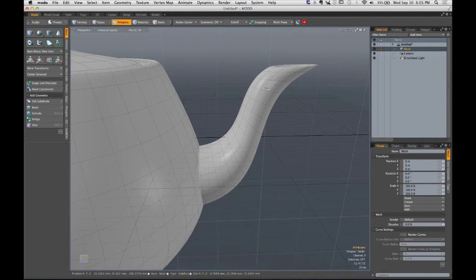now I can go in and you can probably begin to see the highlight color as I roll over all these polygons. What enables me to select the polygon? Clicking it with which mouse button? Left click. Okay, we're a left click centric selection system. If I double click on it, what's going to happen? Now, did it select all the polygons on the teapot? No. What did it select? Only the polygons that are connected or welded to each other. Important distinction to remember.